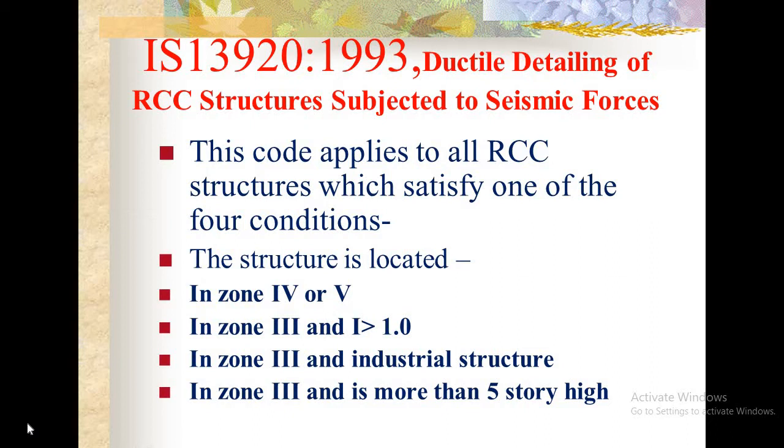Wind load may be higher than the design load of an earthquake, but the actual earthquake load is 10 times greater than the design load. Hence, ductile detailing is necessary to avoid failure.